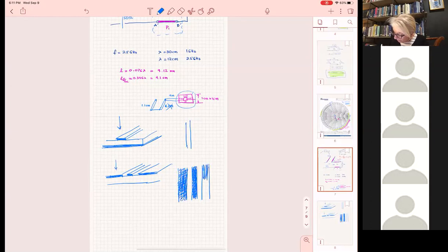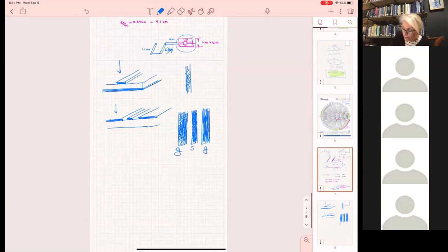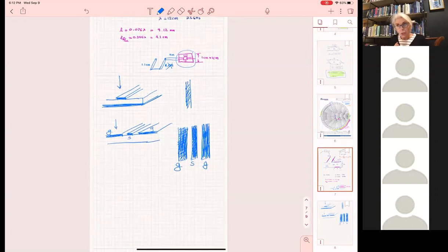That's a coplanar waveguide. Now, what happens when you use microstrip, and what happens when you use the coplanar waveguide? In the coplanar waveguide, because both conductors, ground and signal line, are all on the same surface, ground, ground, and signal, it's easy to short circuit things. And it's easy to put something in series. So, for example, let me put here a series shorted stub in coplanar waveguide.